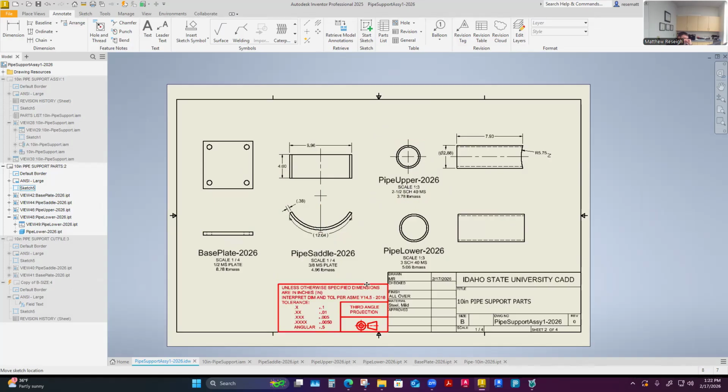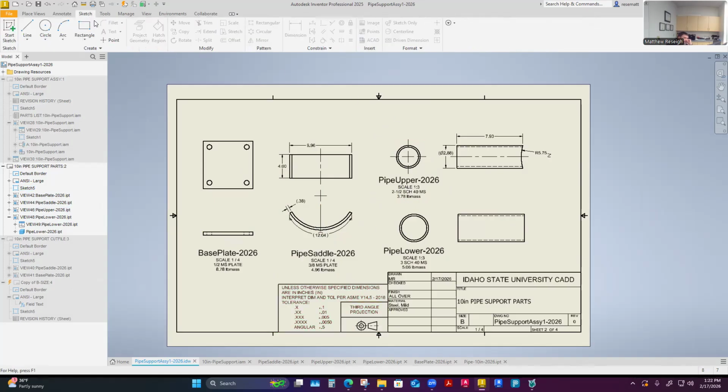But just be careful. Sometimes it's better to separate them with a quick 2D sketch on your drawing, just sketching some unconstrained lines. I usually draw them vertical and horizontal, and I don't usually do odd-shaped sketches to capture drawings. I usually just grid them out. So call that done, you guys. Part 3. I just wanted to catch that.